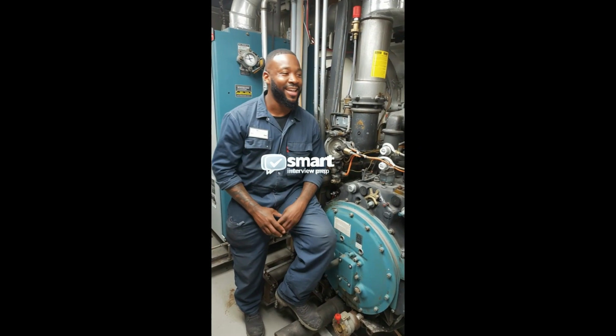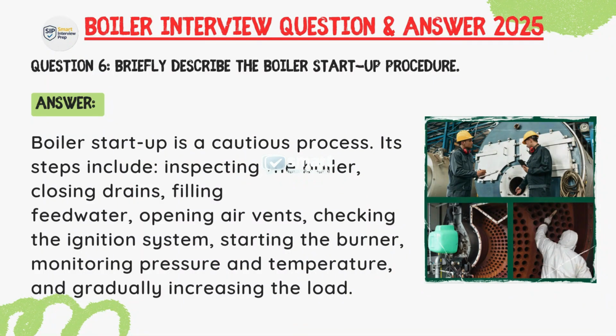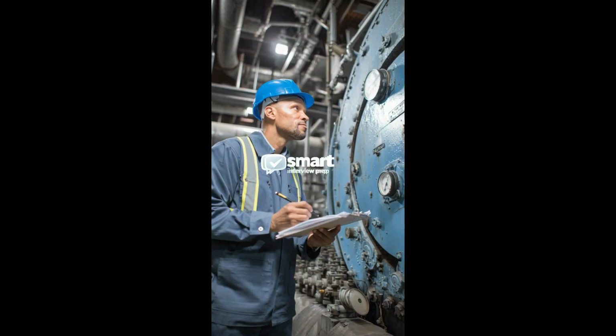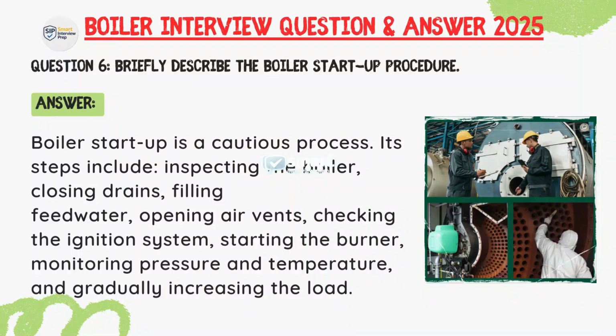Answer: boiler startup is a cautious process. Its steps include inspecting the boiler, closing drain, filling feed water, opening air vents, checking the ignition system, starting the burner, monitoring pressure and temperature, and gradually increasing the load.